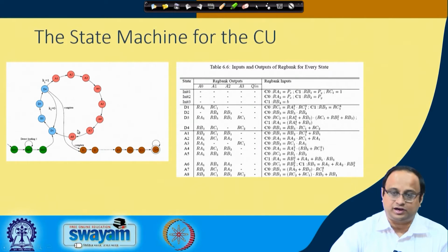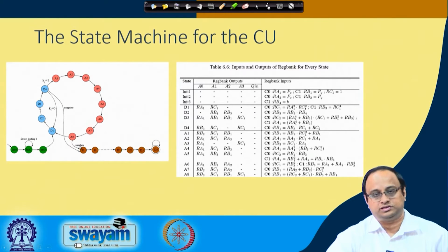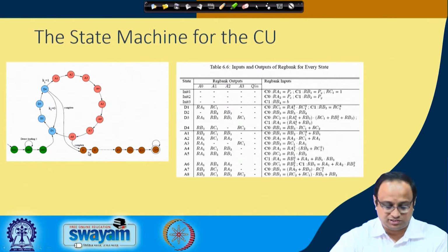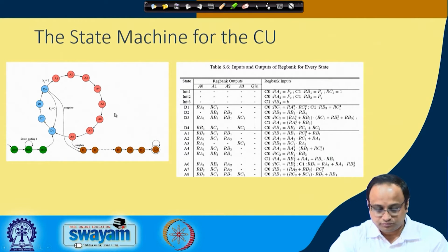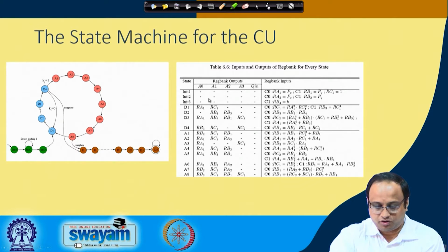But this is conditional in this architecture. Later on we will see this is not a very secure way of doing it, but from a performance point of view this looks fine. So, you take 8 clock cycles for doing the addition. Once you have processed the entire scalar, you go for the final result, where you get the affine coordinates back, and for that you do an inversion. That is shown by these brown circles. For the inversion we have a 24 clock cycle requirement, done by the Ito-Tsujii inversion algorithm. So, these are the different components for doing the operation.